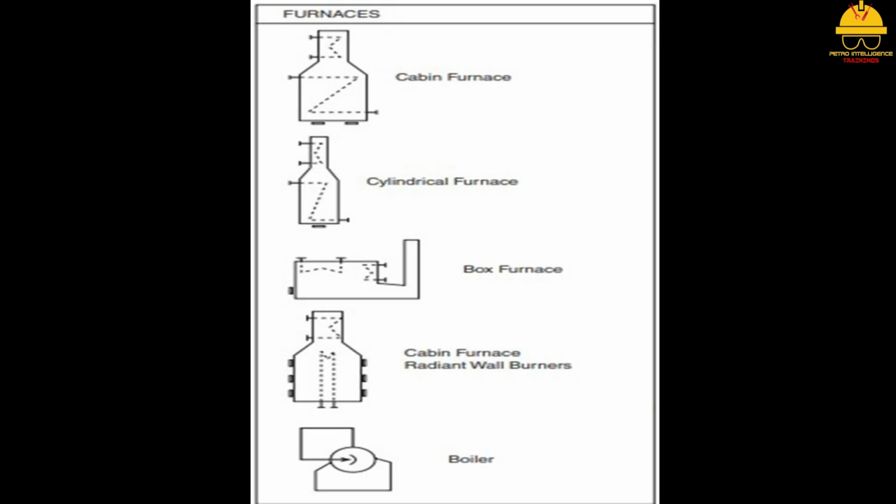The basic components and operation of boilers and furnaces are covered in boiler and furnace trainings. A furnace is designed to heat up large volumes of feedstock for chemical processing in a reactor or distillation column. Feed enters a furnace in the cooler convection section. Heat transfer is primarily through radiant and convective processes. The hottest spot in the furnace is the firebox. Tubes in the firebox are referred to as radiant tubes.